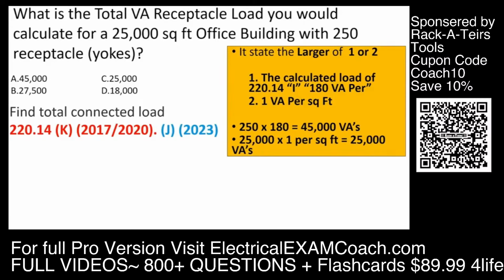Part 1 says that you must calculate it at 180 VAs per yoke, like we learned before. And Part 2 says you must calculate it at 1 VA per square foot. Let's do our first one. We have 250 receptacles multiplied by 180 VAs each. That gives us 45,000 VAs before demand factors. Part 2 says we need to take it at 1 VA per square foot. So we take 25,000 square foot multiplied by 1. That equals 25,000 VAs. That portion of the calculation we're done, but that first part, there is a demand factor that applies to it.